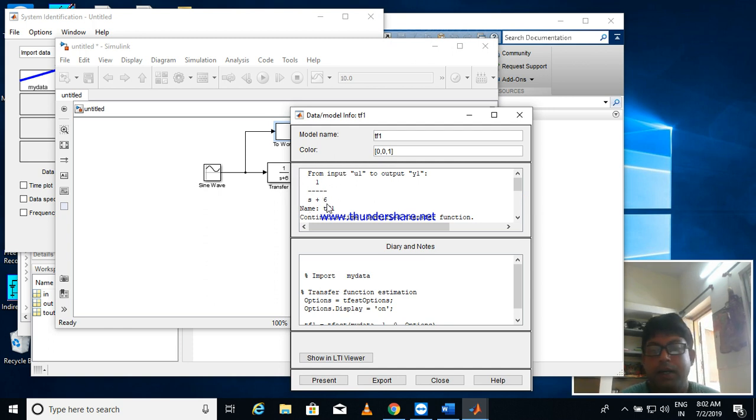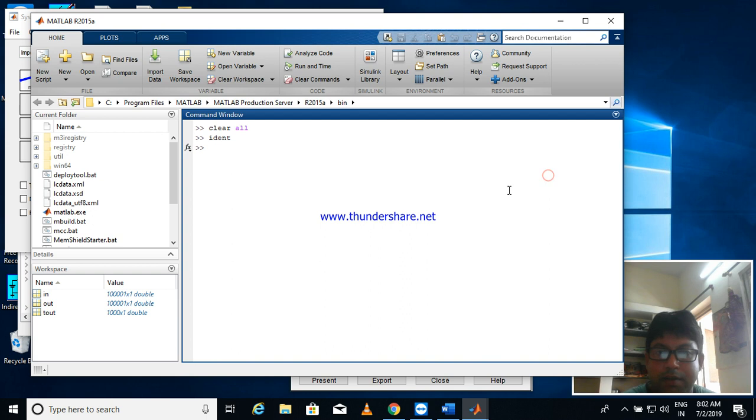Normally, in a practical case, when you are trying to identify a system in a real life problem, you just take the time domain data. It is always better to take the data at a very high sampling rate and give some small perturbation to the system which will not cause any disturbance, and you capture the data. Then it is better to capture the data in CSV format. Then you import that data to the Matlab workspace, and same as whatever I have shown, use the System Identification tool to get back the system transfer function.